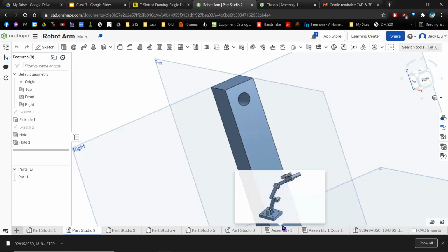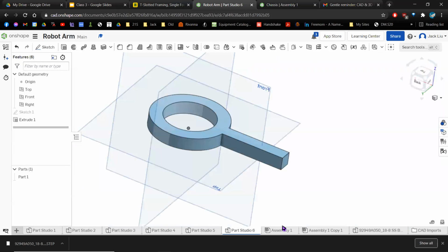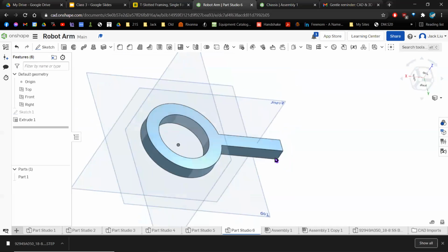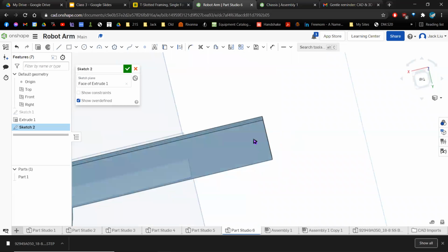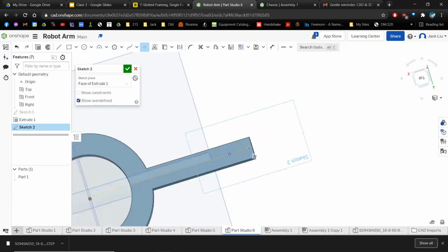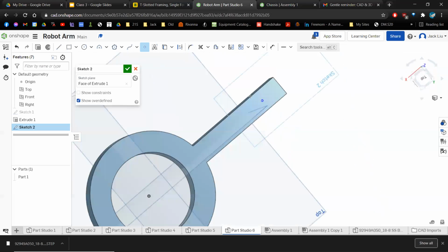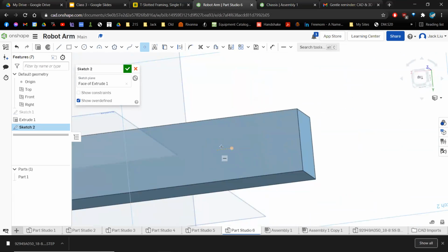So if I go back to my new hand, how do I put a hole here? Well, I can create a sketch right here. I can create a point, and it's already horizontal with this center because I placed it when there was this dotted line. And then I just need to dimension where it is. So I can dimension it from here. Maybe I want it 1/2 inch away.